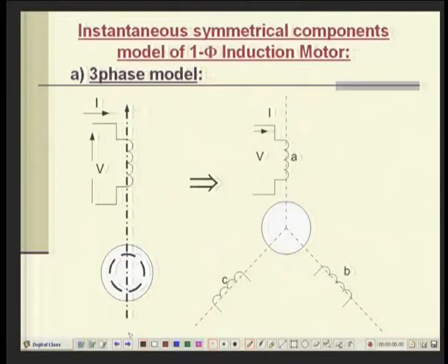If you connect them for the same sequence, then the air gap flux for both the machines would be the same, but rotating the opposite way. But in actual practice, you should not connect them in parallel, you may have to connect them in series, so that the stator currents would be the same and the voltages are not the same. Okay. So, I think these are the things that you need to understand based on this. So, I will quickly go through what we did yesterday in the last lecture.